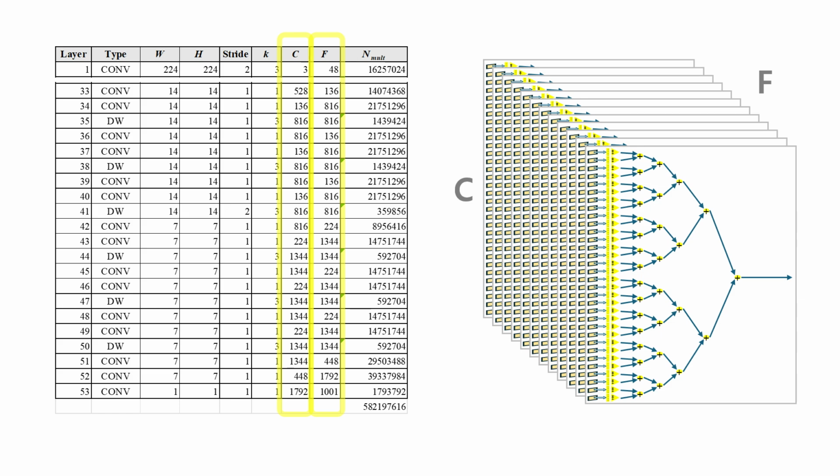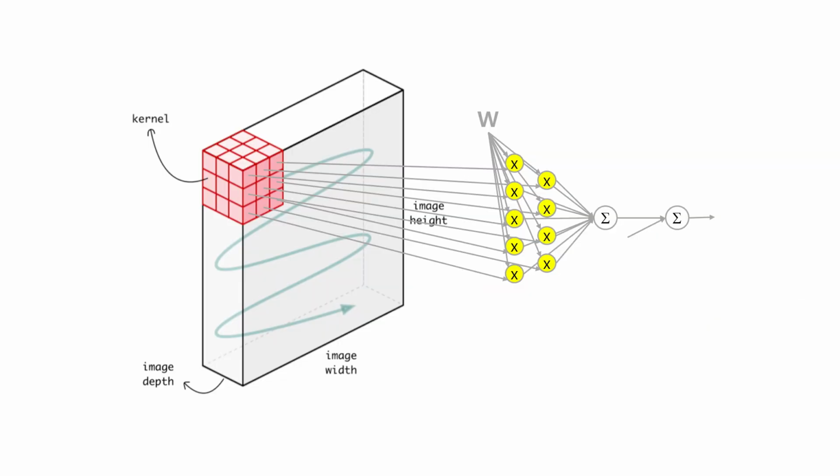The second problem occurs when k is greater than 1, that is, in the case of 3 times 3 or 5 times 5 convolutions. In this case, k by k data from the feature map must be read simultaneously for each clock cycle, but the locations of the data are scattered within the plane space of the input image, making it very difficult to simply distribute them to multiple memories and read them.